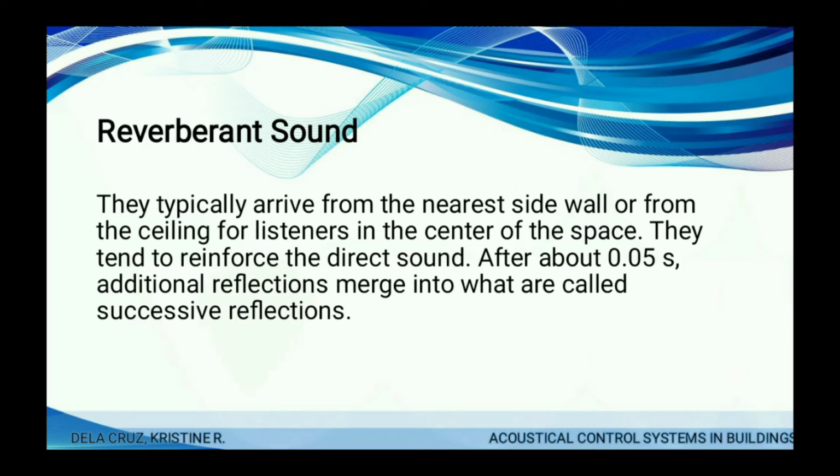They typically arrive from the nearest side wall or from the ceiling for listeners in the center of the space. They tend to reinforce the direct sound. After about 0.5 seconds, additional reflections merge into what are called successive reflections.